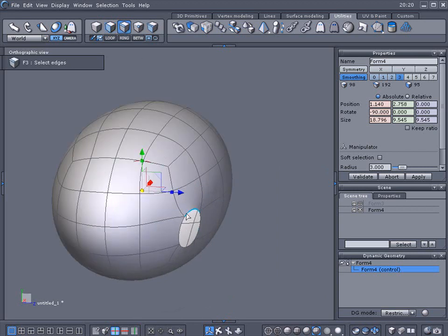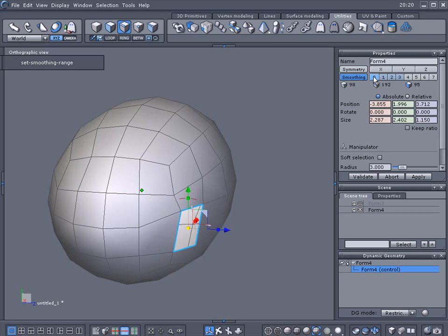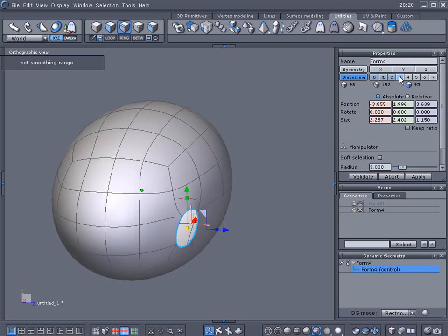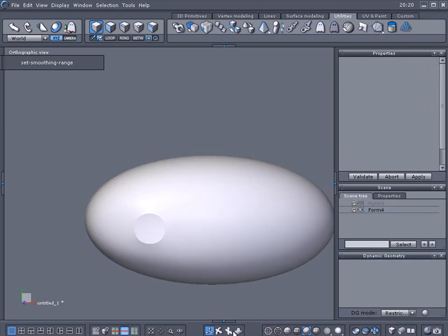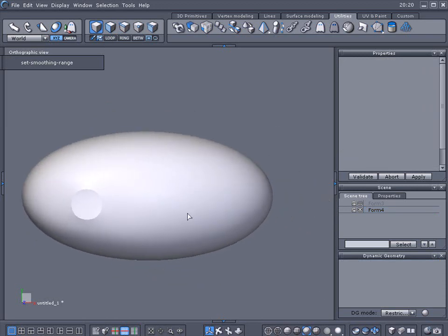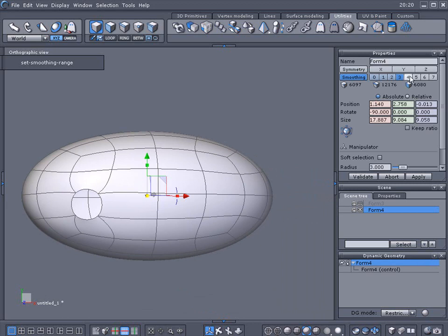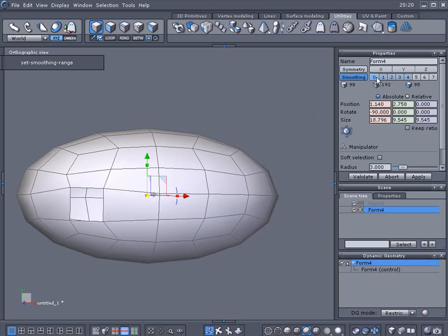We can adjust that if it looks like it's sticking out a little bit too much, and just bring it in just a little bit if you want to. It's probably best to turn the subdivision down a little bit before you do that. And we'll turn on smooth here and take a look at that. That doesn't look too bad. And like I said, sometimes the more you subdivide or whatever you add on here could make this hole a little oblong. So let's go into step 2.